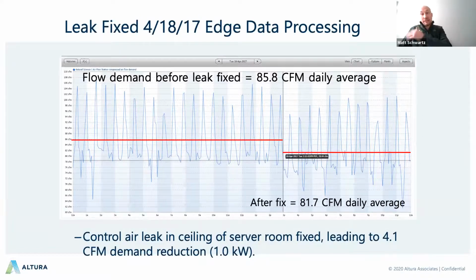We therefore found several other compressors doing a similar thing. And by fixing these small leaks at scale across the campus, we could find the small leaks at the edge, fix them, and analyze big scale, full scale, what was the savings of that? And so those add up when you get these little 1 kW hits and do it at campus scale. And that's just one example.